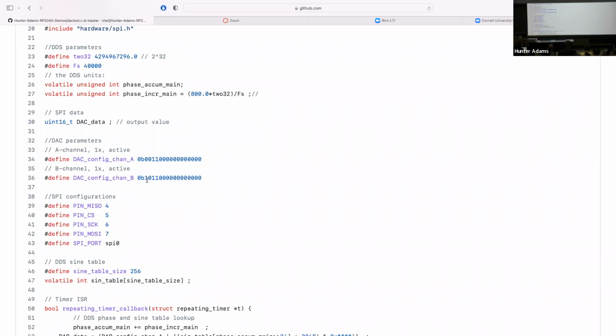It would not be optimized every time it accesses it, because sometimes if you don't add that keyword, it would just ignore, even though it might change. Yes. So what volatile is saying is that you're telling the system that it should go retrieve the most updated value for that variable from memory every time it's used. So we want to tag anything that is updated asynchronously with the keyword volatile.